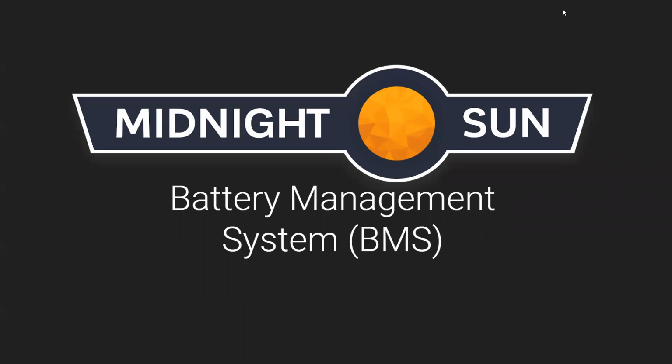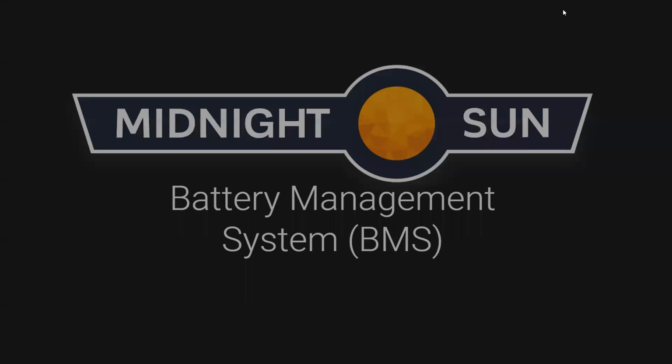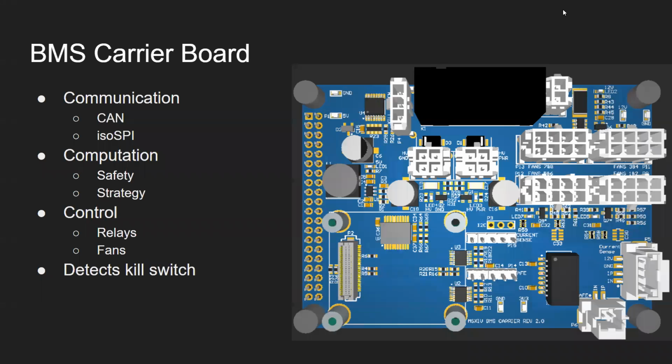Okay, so I'm just going to quickly talk about how we actually measure our battery pack and keep it within safe limits. Our BMS system has 3 different boards in it. The first one is the BMS carrier board, which is responsible for communication. It has a controller board on it that communicates with the rest of the car over the CAN network, and it also communicates to the other boards through ISOSPI. ISOSPI is a differential communication protocol that can be converted between SPI and ISOSPI. It's really useful for communicating to other ICs, and because it's a differential signal, it has a high immunity to noise.